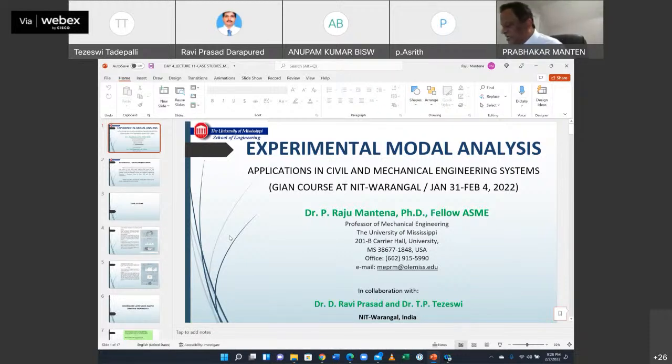The more danger is when that smaller mass and spring starts resonating, the deflection of that mass and spring will be quite large. So there has to be provision, clearances available below that machinery or wherever it is attached, for the free movement of that extra mass and spring, so that it doesn't impact somewhere else. And the spring stiffness should not be so poor that, because of it going into resonance, it will break and tear away. Those are other issues which need to be taken into account when designing tuned absorbers.